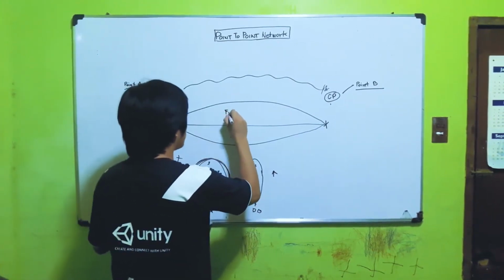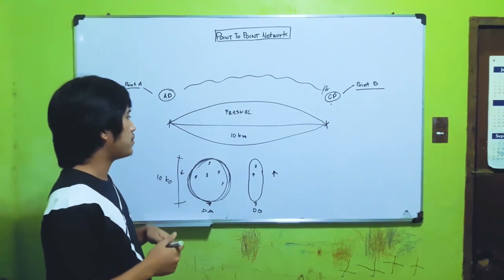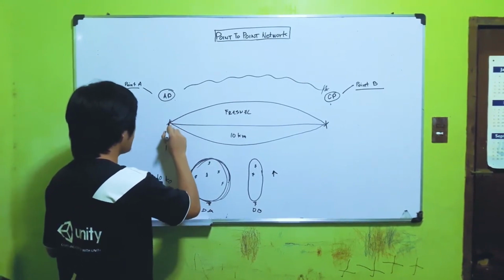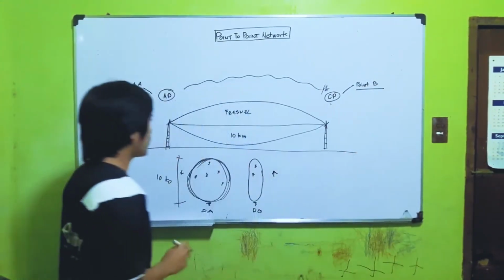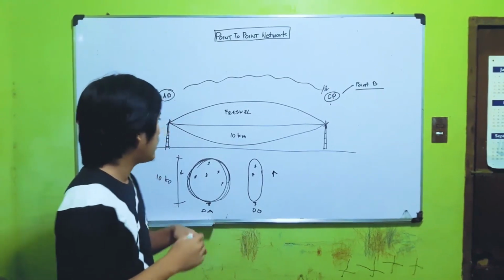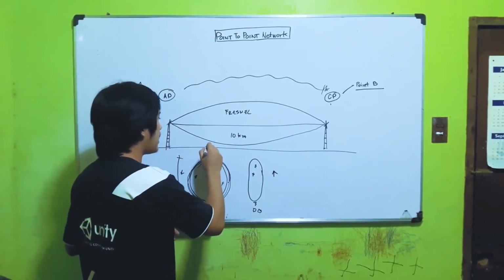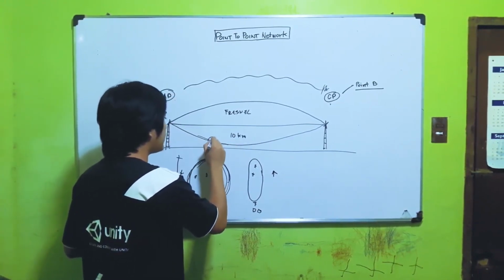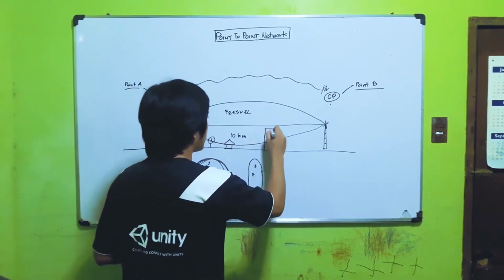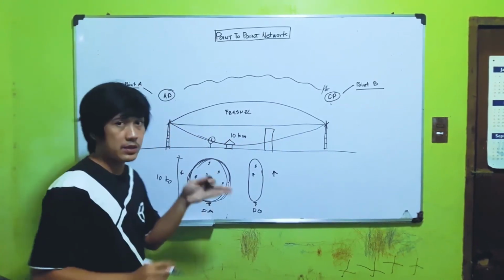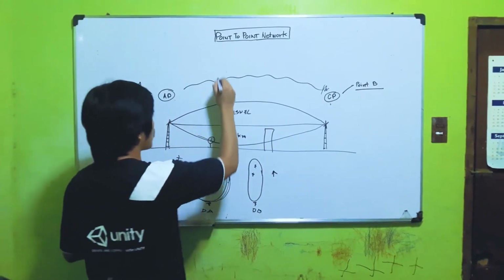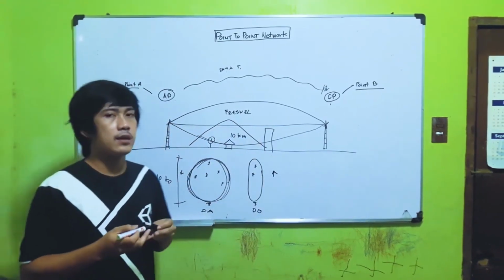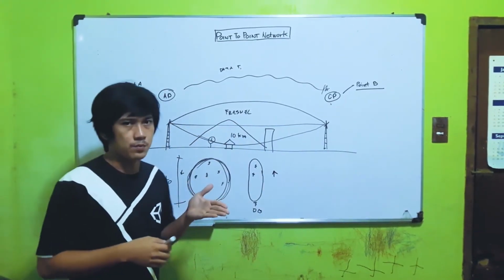So going back to the Fresnel zone. When we talk about Fresnel zone, the object that is involved is an antenna. Why? Because, for example, this is the ground. To be able to transmit the data fully, we should eliminate any object that is interfering within this area, the Fresnel zone. Any object that interferes, a tree, a house, a building, can decrease the speed of the P2P, especially if there is a mountain that is surpassing the line of sight. That is a very big problem when we talk about the Fresnel zone.